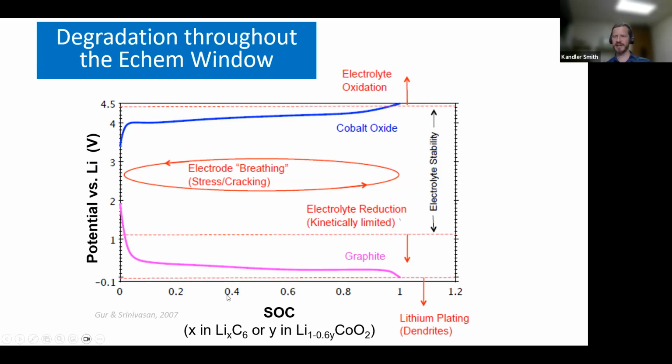There's a couple rules of thumb that don't always hold up, but say your battery has 2,000 cycles lifetime. For each halving of the state of charge window, so if you reduce your depth of discharge from 100% to 50%, there's like a quadratic improvement in cycle life. So if you cut your state of charge window in half, you'd get from 2,000 cycles up to 8,000 cycles, if that makes sense. That's one rule of thumb you can use.